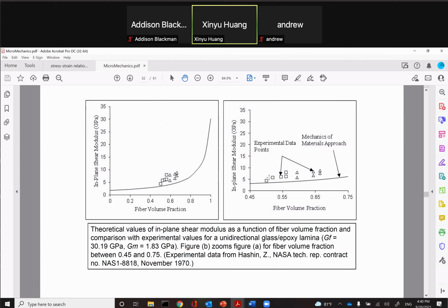So think about the process of these happening. The material deformation is a collective property, an average of many atomic bonds deforming a little bit. If you do the right averaging, you always get close. And the failure is really controlled by a few defects. If you talk about failure of materials, it's a weak interface, voids, resin pockets, defective fibers. It's really hard to frame in any analytical models. Very hard.